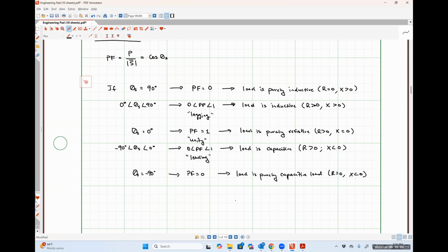Meaning that if you had an inductance whose impedance looked like plus J5 in series with a capacitance whose impedance looked like minus J5, those guys cancel each other and that network as a whole will operate at a unity power factor. But I'm not going to give you anything that has both capacitance and inductance and ask you that kind of question, just because I don't want to confuse anybody or make you go through that much effort. Okay.